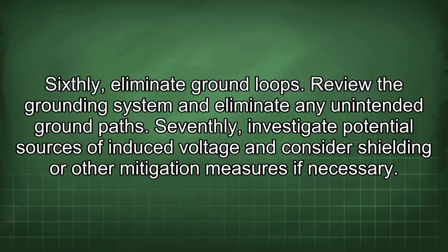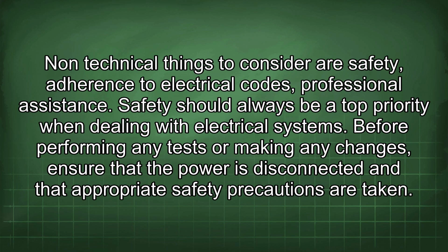Sixthly, eliminate ground loops. Review the grounding system and eliminate any unintended ground paths. Seventhly, investigate potential sources of induced voltage and consider shielding or other mitigation measures if necessary. Non-technical things to consider are safety, adherence to electrical codes, and professional assistance.